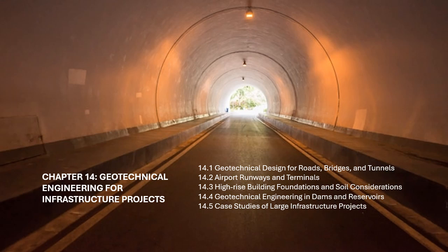Key considerations for foundation design and site selection include site investigation. Detailed geotechnical investigations are necessary to characterize the soil and rock properties at the dam site. These investigations may include soil borings, laboratory testing, rock core sampling, and geophysical surveys. The purpose of these tests is to evaluate the strength, compressibility, and permeability of the foundation materials.